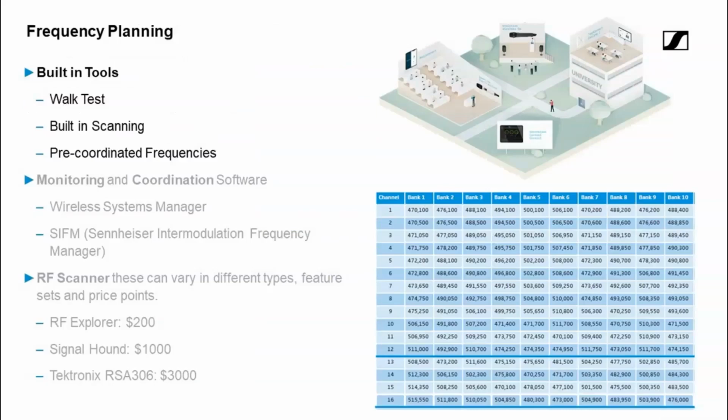Okay. So one of the first things in that regard is let's do some walk tests and see what kind of buildings are made of, what kind of transmission I can get from one room to the other. If I do have an outside performance area, maybe I'm going to have 30 or 40 channels of UHF here for this outside performance area. Is that going to be getting into the buildings here?